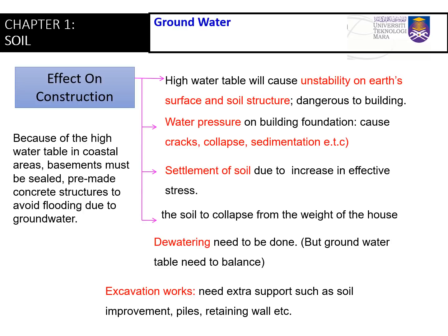So when you have disturbance, especially water pressure, it has pressure, right? Especially if it passes through very narrow gaps, the pressure will be high and it can disturb your building foundation and cause cracks. So when it cracks, it means the loads will not be transmitted further down. It will stop at the crack. So the reading will be 0. No load will be transmitted. Then you will have settlement, like I've mentioned before.